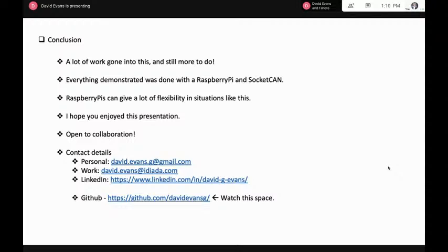And I thought that in ISO-TP, the flow control message you send, I could try a little man-in-the-middle attack by telling the radio module to essentially terminate the rest of that payload, which is pretty much just the LCD module pretending to say, I'm not interested in that message, which is part of ISO-TP.